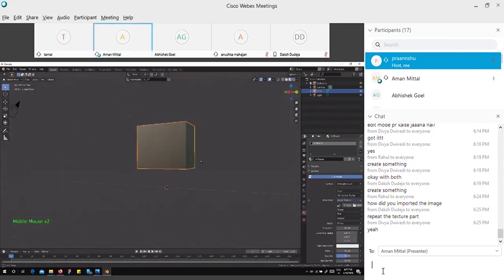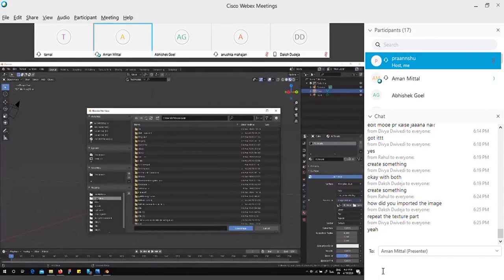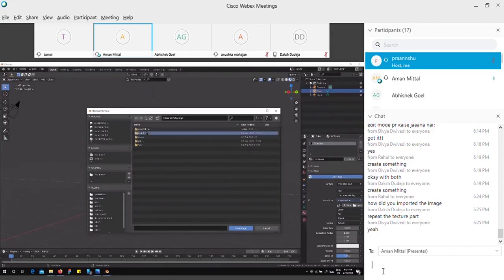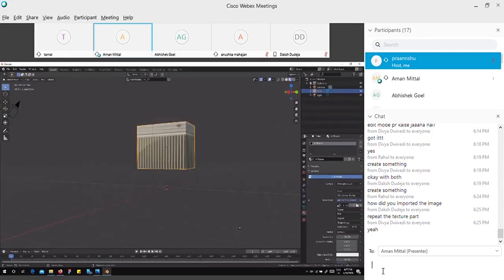Now below that image texture option, we will open the image where you have downloaded it. Most people must have it in the download folder, but I downloaded it on my desktop here. Select the image you want to give the texture from, and just click open image.